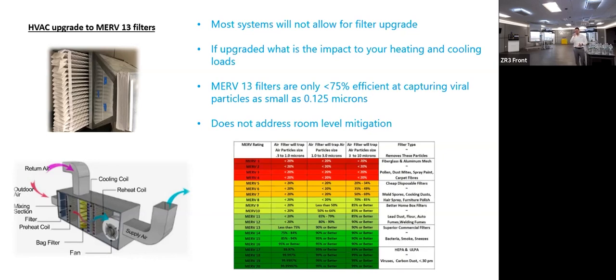That tells a small portion of the story. Yes, HEPA filters are efficient. Any H14 HEPA filter is rated at 99.997% efficiency. Again, that doesn't tell the whole story. How do we get the concentration of the pollution to that unit? What is the overall load reduction that we're able to create within that room? That tells you the overall performance and the efficacy of the system.